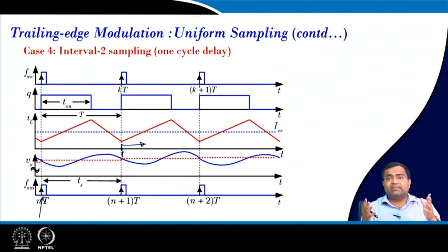This will penalize heavily in terms of nonlinear phenomena, and we need to tackle how to make your design stable even with this delay, and what could be the alternative arrangement even with this delay, because you may not need a very fast ADC. One possibility is to increase the sampling rate when there is a transient, or you may create an additional path to bypass and avoid such a large delay during a large transient. So, there are many possibilities.